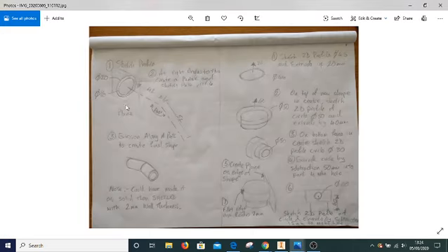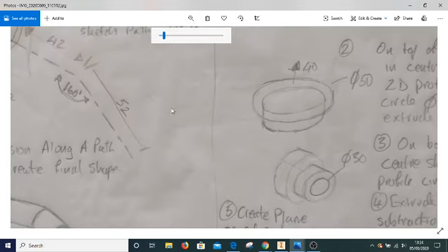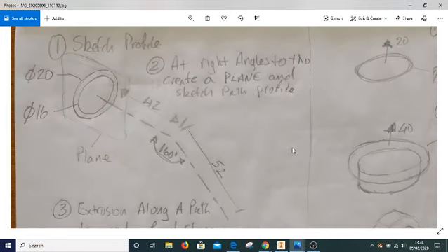the connecting pipe. As before, I'm going to attempt to zoom in. Shows what we're doing here. Right. Step number 1, I sketched the profile shown, which was a 20mm diameter circle and the 16mm diameter one concentrically inside it.